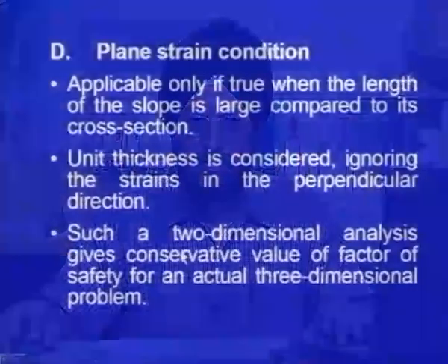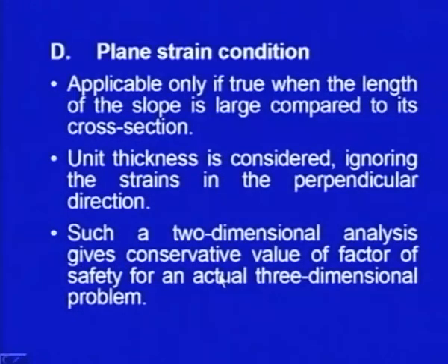Now, this is a 2-dimensional analysis, and as I told you, if it is not meeting the requirement, you have to do the 3D analysis, and this 2-dimensional analysis in general gives conservative values of the factor of safety for an actual 3-dimensional problem. So, I am stopping here itself.